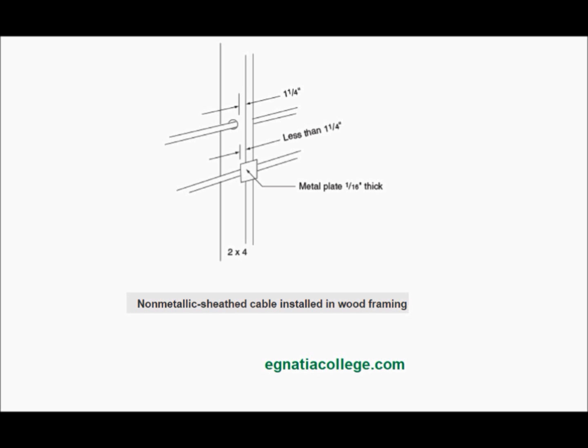Many frame buildings are constructed using some of the elements of advanced framing, but not all of them. Notes on plans and details will describe these elements where they are to be used. Examination of the first floor plan and the detailed drawings of this house shows that the walls are framed for maximum efficiency. Several details indicate that the studs are 2x6 at 24 OC.